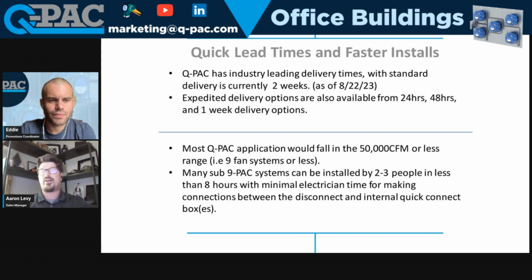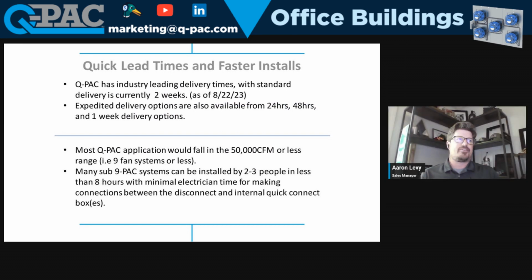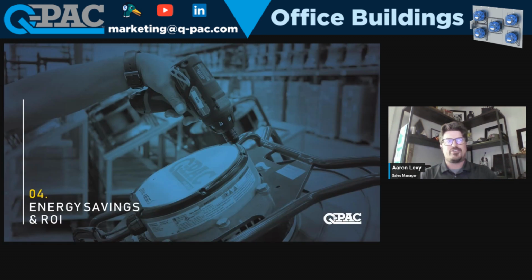These things have been around for almost 20 years now, if not more. That technology has improved drastically over that time, very much like VFDs did when they first came out to what they are now. So ECs don't tend to be as big of an issue as they used to be. It's just different technology that is becoming more and more of a standard.